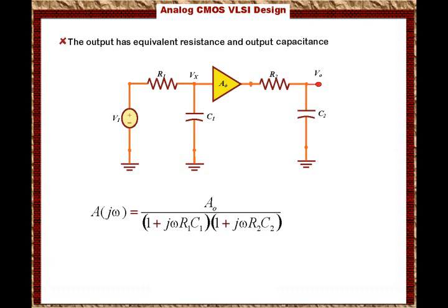So far what we said now is how the frequency response behaves for the amplifier if there is a single time constant circuit at the input and a single time constant circuit at the output. And this is a practical circuit, and you will see that we will use the circuit to develop the frequency response of the amplifiers that we have learned so far. We are starting here by saying that the frequency response of the amplifier is affected by the RC time constant. We have an RC circuit at the input and an RC circuit at the output, and they both affect the frequency response of the amplifier. That's all we're saying.